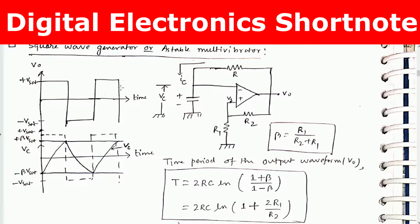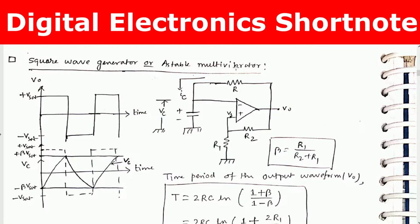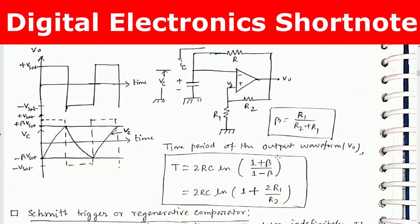This is a square waveform, and this is the voltage across the capacitor. This is basically a multivibrator, so it will have some frequency and a time period as well. The time period equals twice R C ln of 1 plus beta by 1 minus beta, where beta is given by this factor.